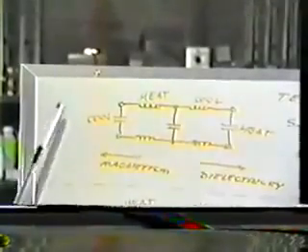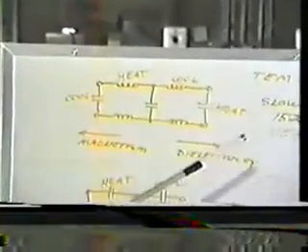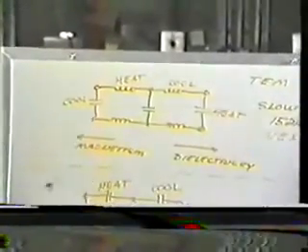We find with the TEM, as the dielectric induction builds in intensity, it's always fully across each capacitor, which of course causes the capacitors to fail at the output end, and you can never get high voltages. Same thing with the two-wire transmission line. If you try to get it to resonate, obviously the wires are going to flash over at the output.